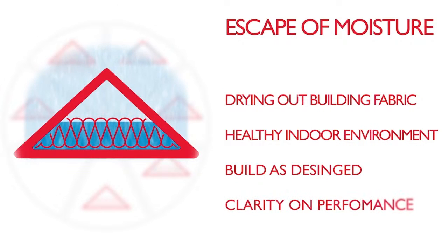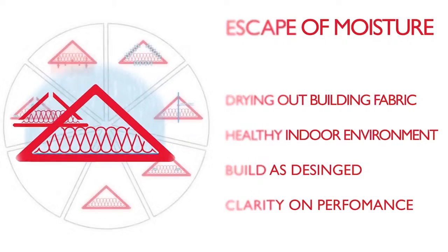There can be substantial differences in the performance of apparently similar materials, which product literature and different test methods do not always make obvious. While CE marking and the Construction Products Directive have gone some way to clarifying and standardising testing and the presentation of information, third-party certification specific to the proposed application remains the most effective way to ensure design criteria are met.